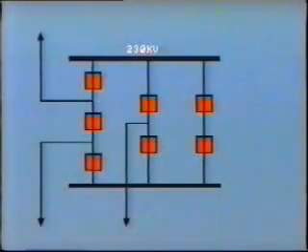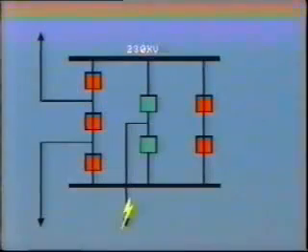Protective relays and breakers operate extremely fast. They can clear a fault in just a fraction of a second. Unless we can capture fault data and reconstruct what happened during that very short time frame, we would probably never be able to pinpoint the cause of relay or breaker misoperation.